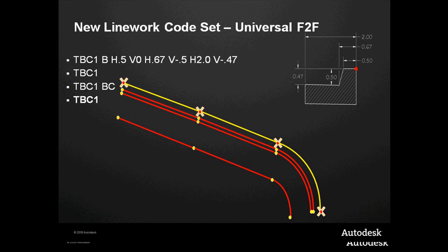But in the event of the curb where it's not going to be a mountable curb and it's going to be ground out, what we can do is put in a code to tell it to stop the offsets. We can do the driveway and then start the offsets back up on the other side, or a different level of offsets, and they'll pass through. Okay?